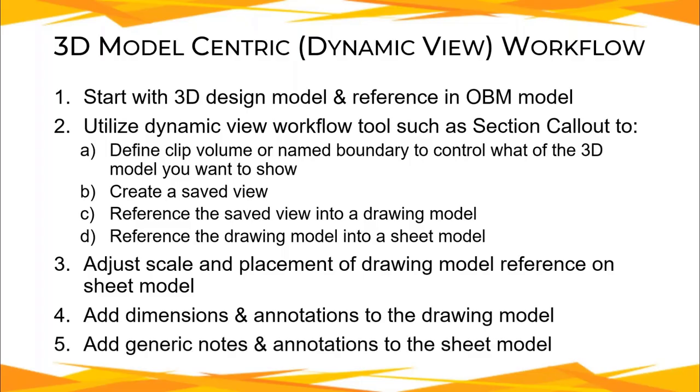And then you go back to the sheet model and add any kind of generic notes or annotations to that sheet model that are not view specific, something like, see sheet B1-22 for reinforcing details or something like that. That kind of stuff would go in the sheet model itself.